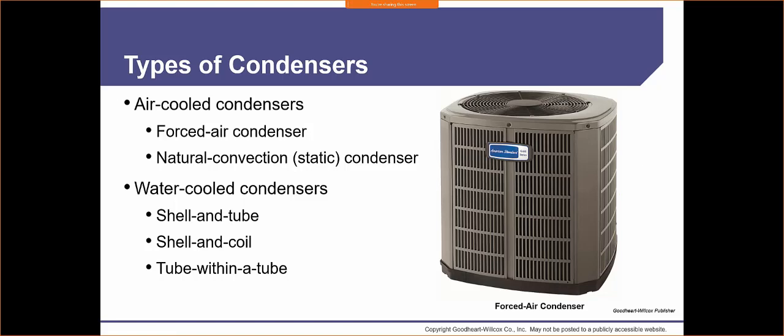They're like these little, I guess, finger prickly looking things, and they're really great at dissipating heat. The problem is they get full of cottonwood, different grass clippings, anything else associated in the yard, and they start to plug up the fins of the units. If the fins get plugged up, we get less air flowing through, less heat transfer, and that leads to problems.